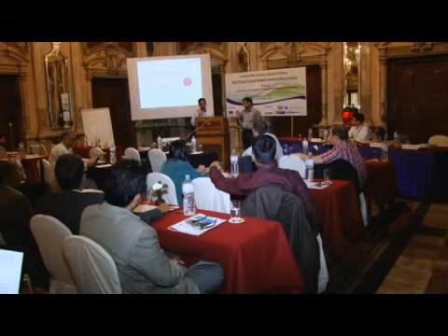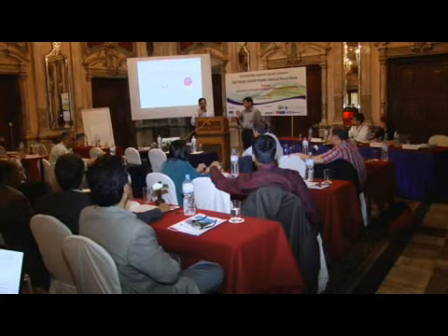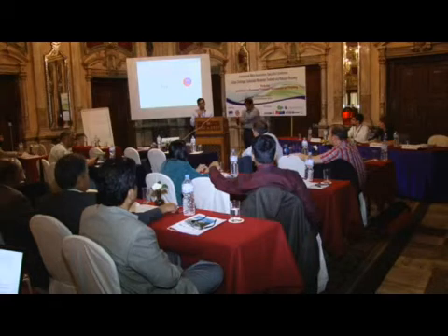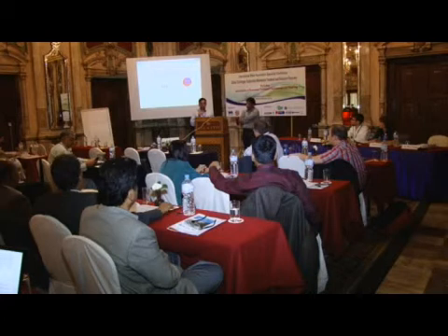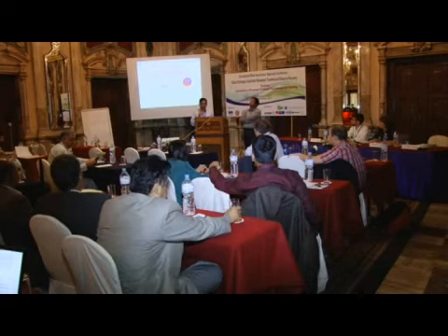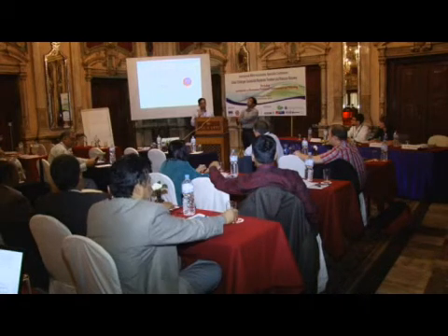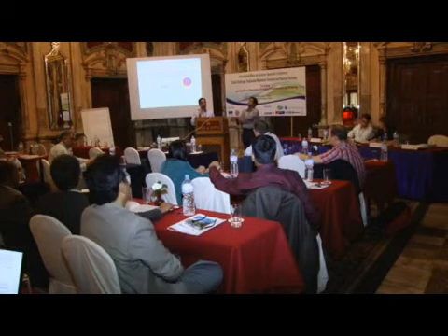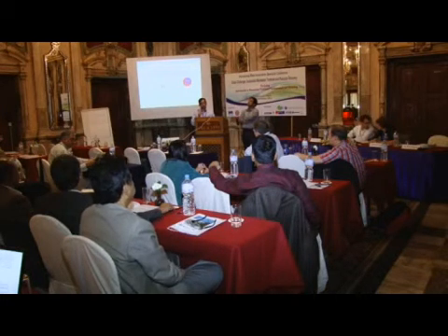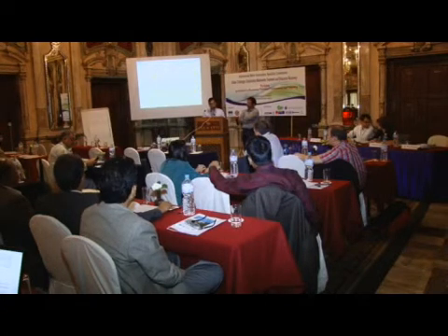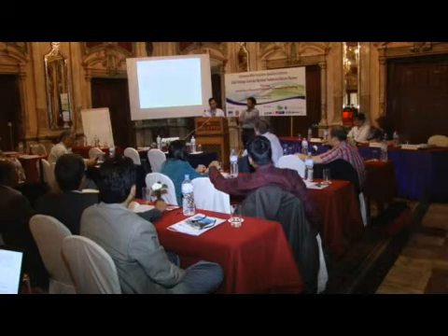There are some disadvantages of methanol, including lower kinetics, but we found in New York City that we had to shut down methanol operations because of safety, and we have since gone to glycerol. There are waste streams containing glycerol. As the biodiesel market accelerates, a lot of biodiesel waste has glycerol and traces of methanol as well. So that is something that has been tested. It's fairly widely applied. In some cases, I would also recommend considering fermentation of some of these streams that I showed you.